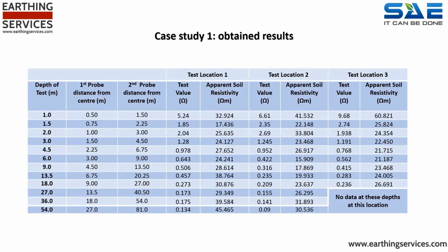For their evaluation, 5 conductor variants were installed, and this was done prior to processing the data set obtained from soil resistivity testing. If we consider that so many people install earthing components blindly, both in terms of driving rods into the ground, which is blind even if scanning has been completed, and blind in terms of knowledge of how well the ground mass will handle electrical current.